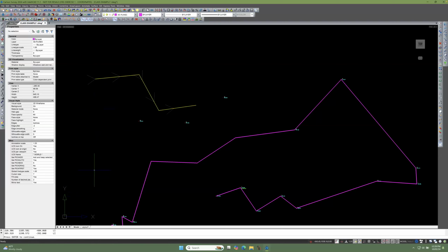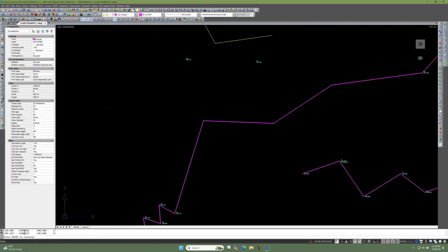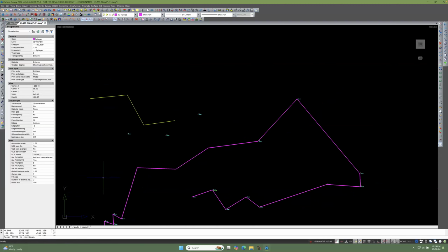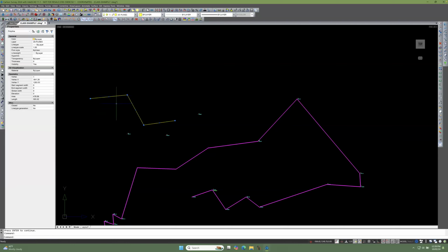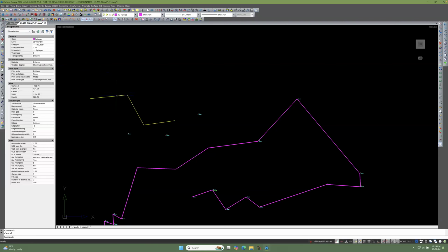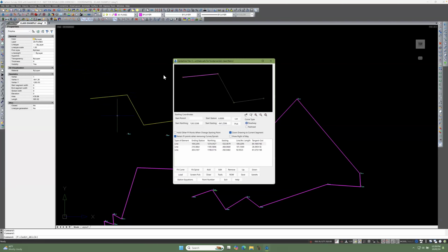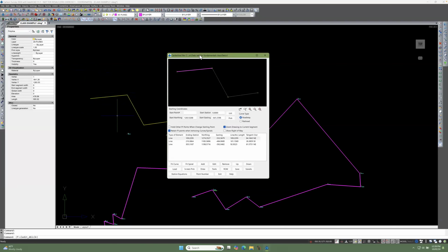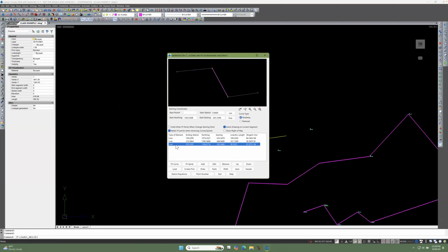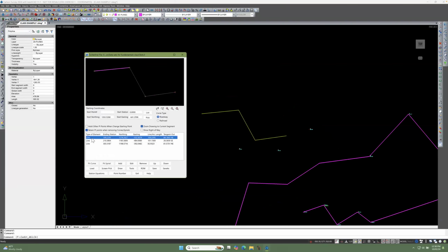And then it tells me some stuff here as to where it found everything, and then press enter to continue. So I'll hit enter. So now I have a centerline file. When I select it, it's still just a polyline, but if you double click it, look what happens. It's no longer the p-edit command. It's this Carlson centerline editor. And if you go to each of these segments, you're going to see it show up in your field here.